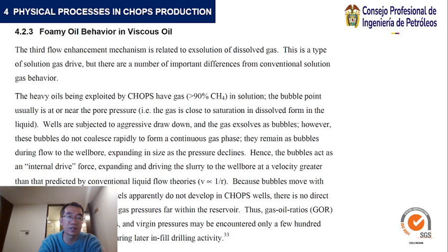The heavy oils being exploited by CHOPS have gas in solution. The bubble point usually is at or near the pore pressure. Wells are subjected to aggressive drawdown, and the gas exsolves as bubbles.